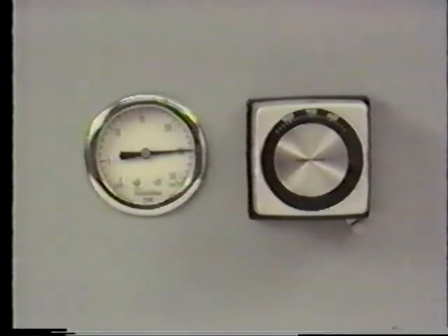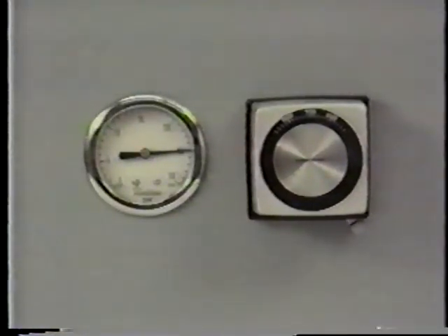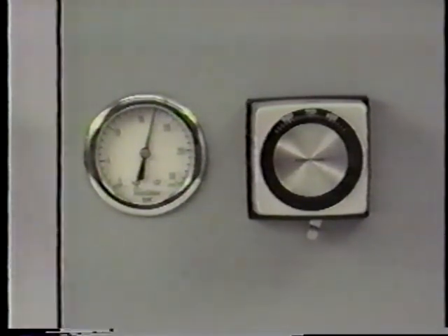A thermostat that has been indexed to the day cycle can be manually reset to the night cycle by returning the lever to its original position. Or it can be left in the day cycle and will automatically reset itself when the main air pressure returns to the day cycle pressure.